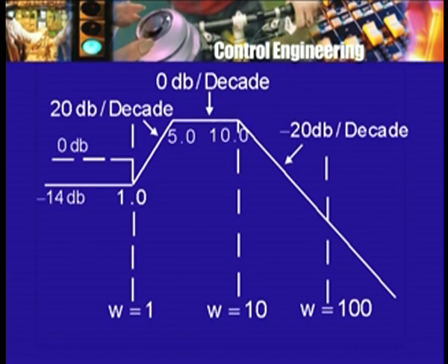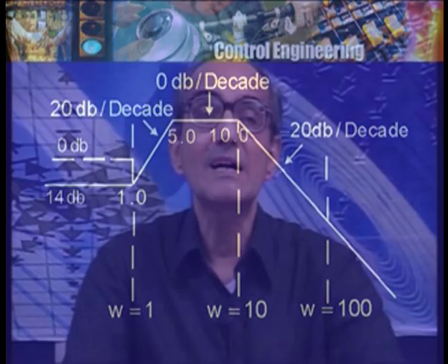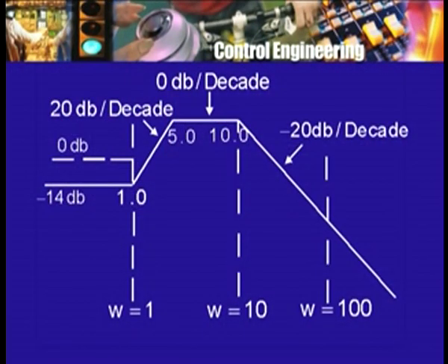No. Why? Because the second pole will play its role, starting with what frequency? Starting with its corner frequency, which is 10. Now, if I show it on this scale, then because it is logarithmic, 1 and 5, so 10 may be say somewhere here. So, up to this point this is a good approximation. Now, beyond this point 10, the 0 of course has its own contribution, the first pole makes its own contribution.